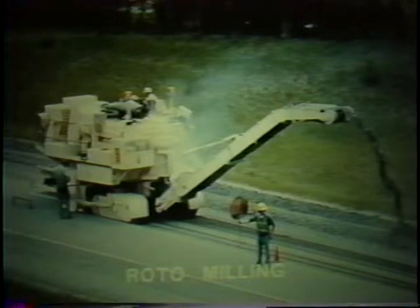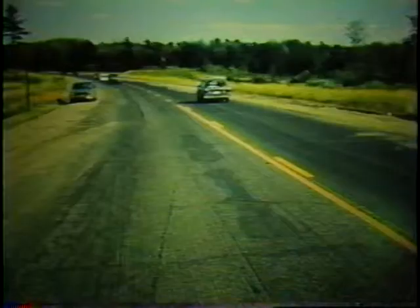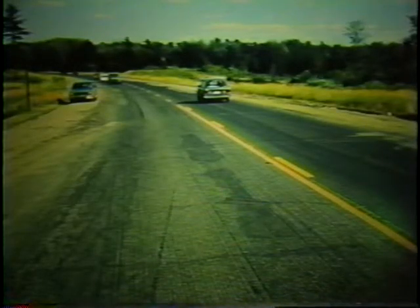Milling is a successful method of refurbishing highways. The old surfacing material is removed first. In that way, the thickness of the roadway is not increased, and the basic minimum clearances can be maintained. A small amount of new asphalt and mix are relaid on the milled roadway. The cost effectiveness of this operation has made it extremely successful, so that it is being used on many miles of highway. A milled surface can provide acceptable friction even before the new surface is applied.